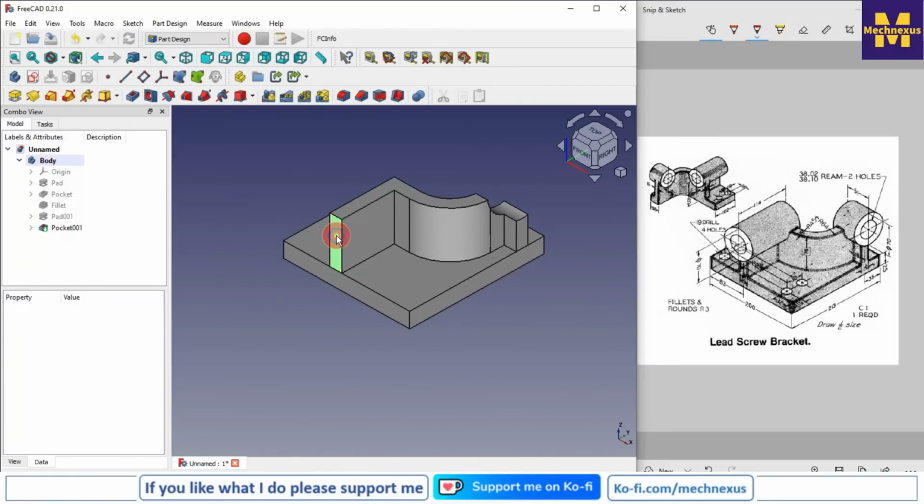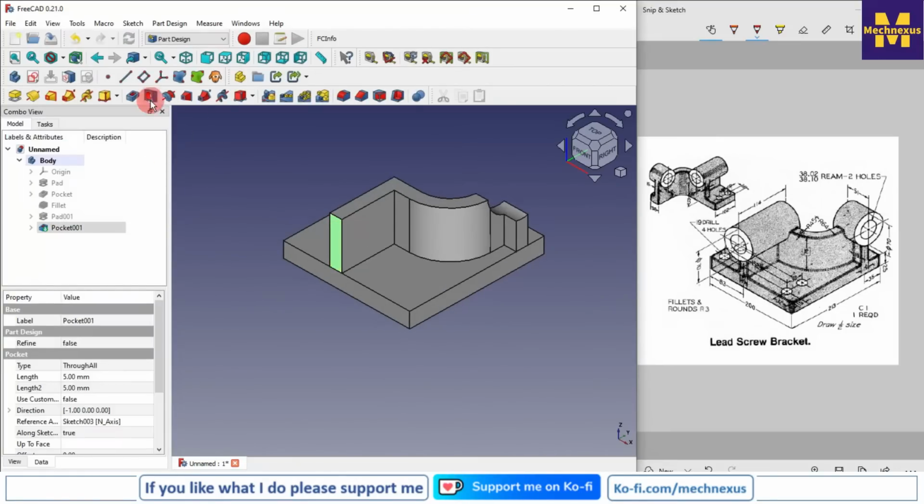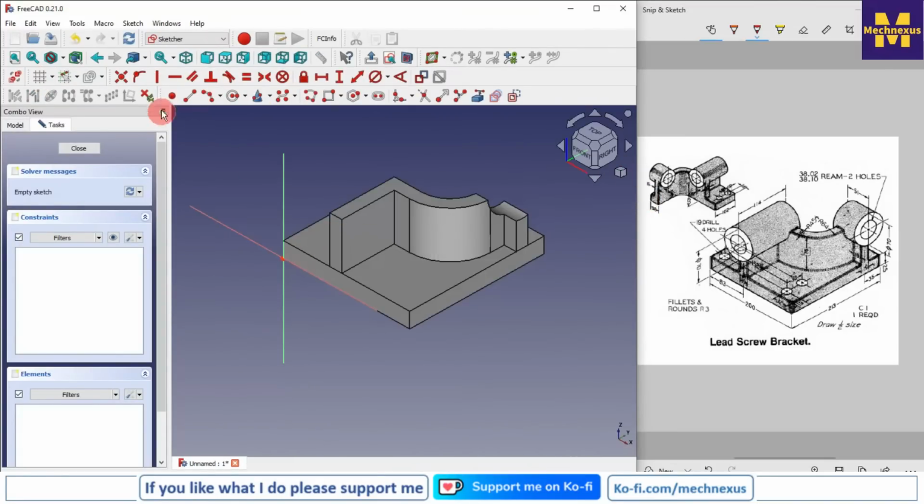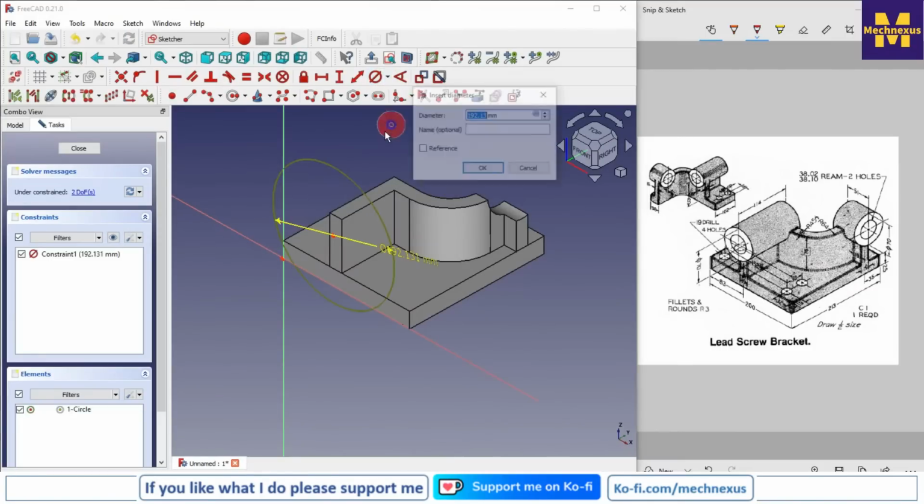We will do the same procedure here. We will select the face and create a sketch, and here I will create a circle, and I will give the diameter of 70.